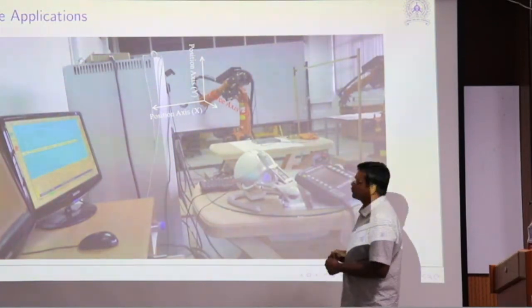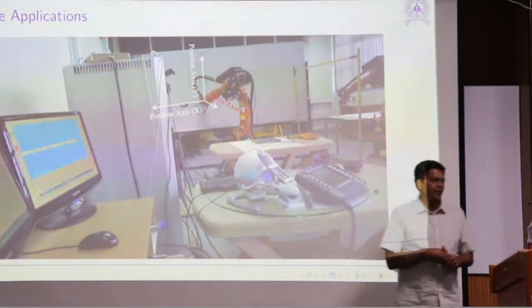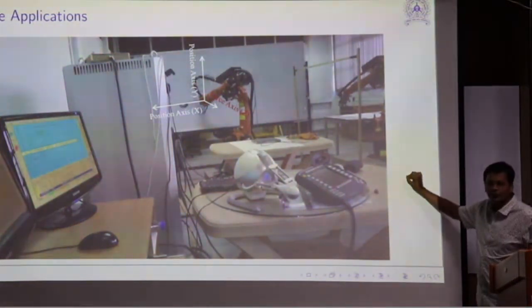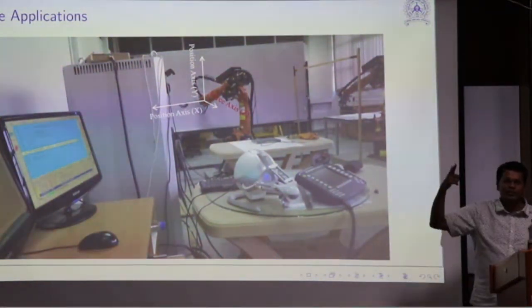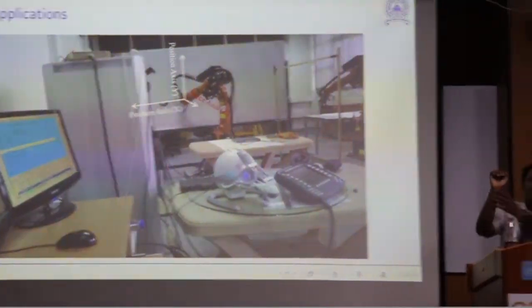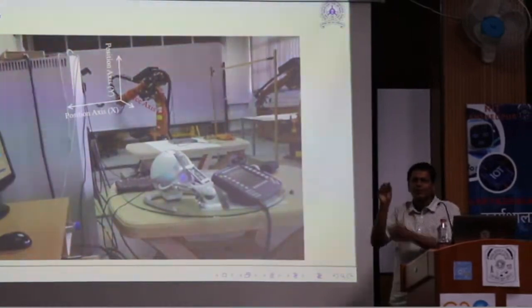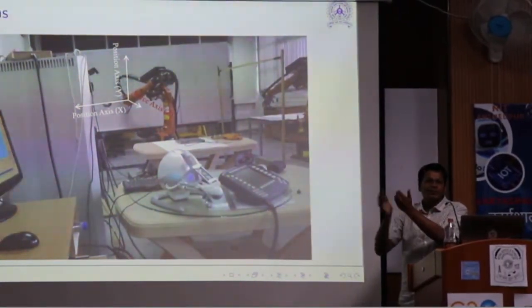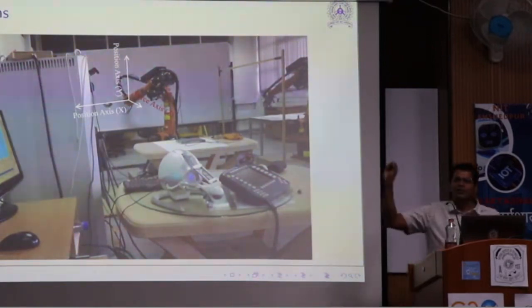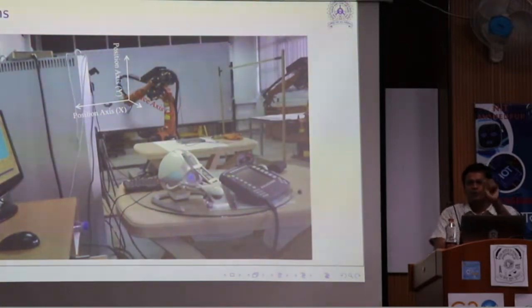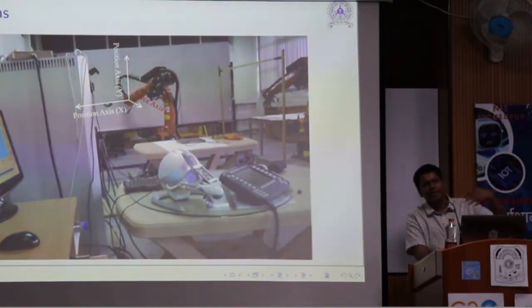We tried doing it with a robot, right? But normally, to maintain that constant force, otherwise your chalk will break, you need to have a force sensor at the wrist somewhere over here, so that it can feel the forces. You can create a closed loop and, using that feedback, you can control that force, right? 2 Newton, 3 Newton, जो भी चाहिए उतना exact amount of force you can maintain, or you can have some additional compliance.